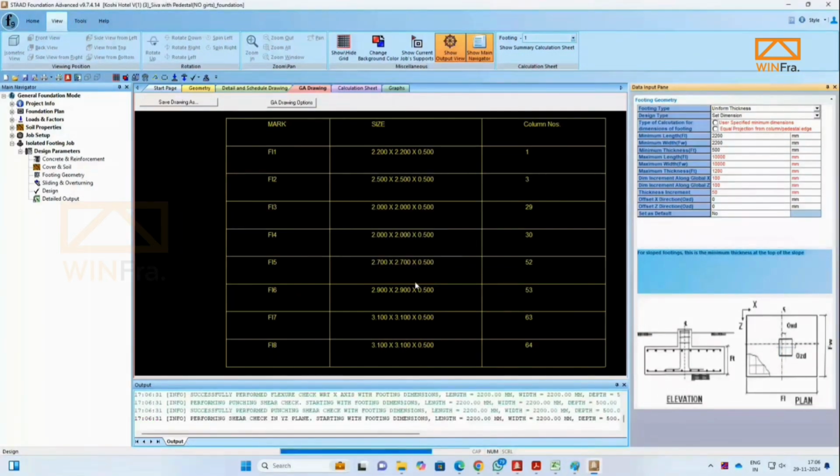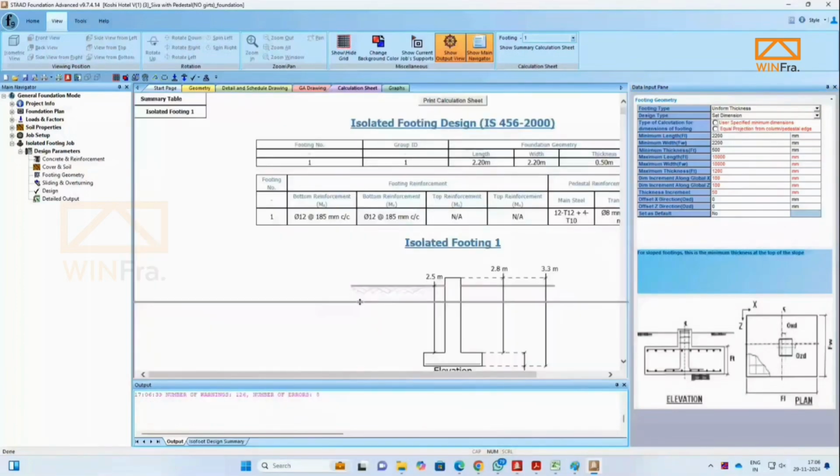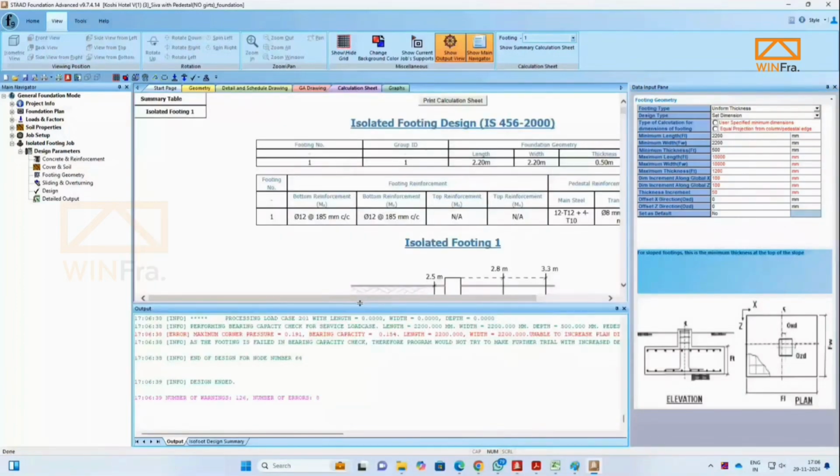See, you can see that there are a number of errors. If you go up, STAAD Foundation doesn't have any command file or anything for you to work on. You'll have to use this space to understand what the error actually is. It will show everything here only. There will not be any command file. So if you have to make load combinations, you will have to manually add them. There is no command file here.